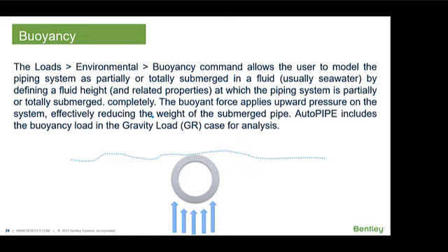You have a lifting, for example, here. Basically, I remember when I was in my first years designing, I did it with a spreadsheet. It's not so different, not so difficult, right? You have the weight of the pipe, kilograms per meter, the density of the water, and so on. And you calculate whether you have lifting or not.